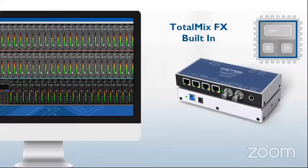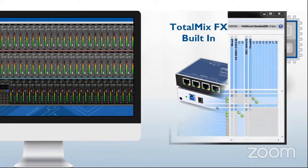They each include Total Mix effects built in on an FPGA chip, which is actually built into the hardware. And that mixer is an amazing routing tool. I think it's a 128 channel matrix mixer that allows you to route and sum and bus streams, whether you're dealing with Dante or AVB, in some very flexible ways, which you cannot do with a typical Dante controller.